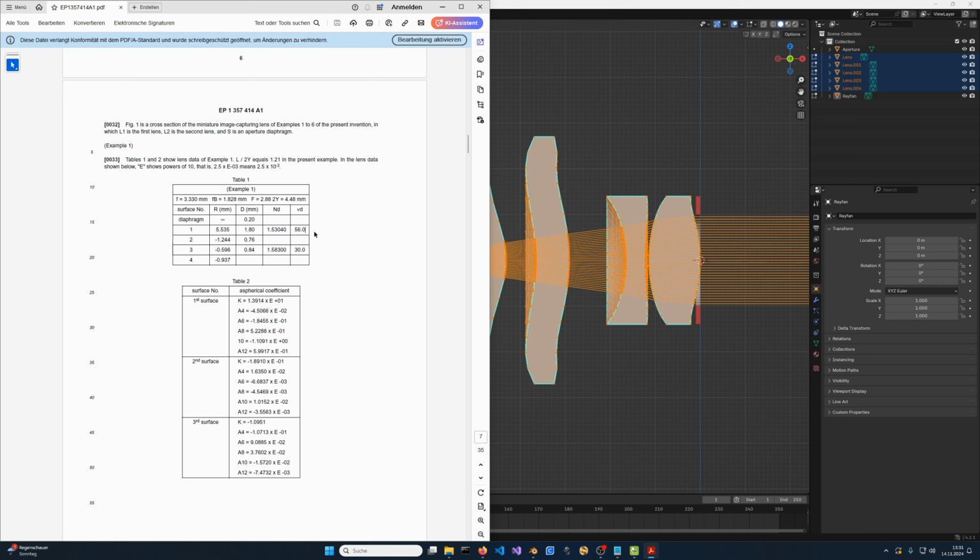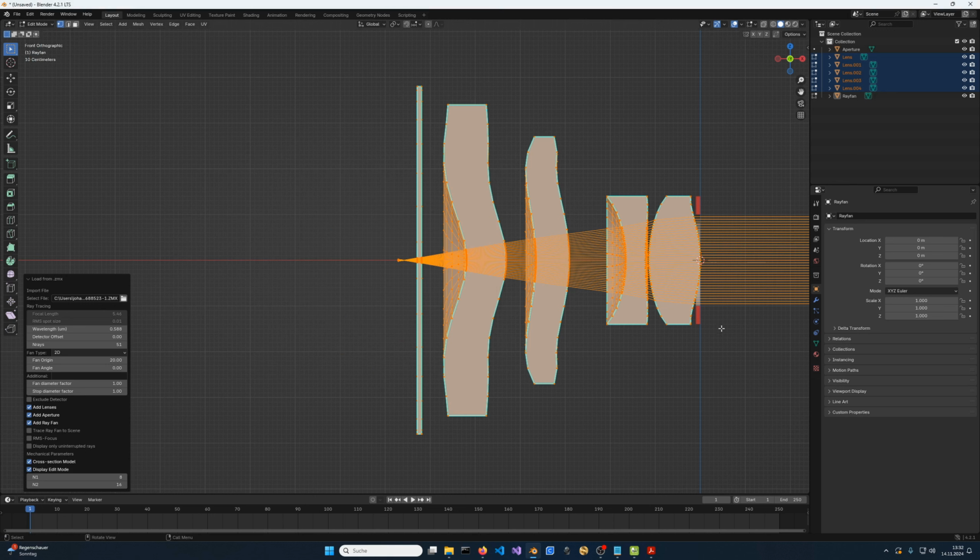Now, the other way to specify a glass in a zmx file is not using a custom dataset like this, but explicitly specifying the name of a commercially available material from some glass manufacturer or some other material manufacturer, or a scientific source for materials. Either a custom dataset like this or an explicit material specification. Using an explicit material specification is actually best, because then you can look up a more precise data curve for the refractive index as a function of wavelength, and thus get a better ray tracing result for polychromatic ray fans, which means considering the full white light spectrum, for example, and not just a single wavelength, which is what is actually happening in the sequential ray tracing as shown here.